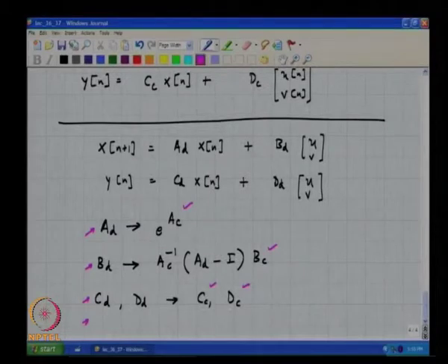So, this simulation technique that we have just discussed will not be accurate for high frequency excitations. These high frequency inputs are perfectly legal inputs to have in a continuous time delta sigma, but this simulation technique is not good enough for that.